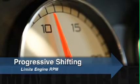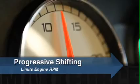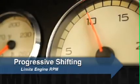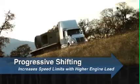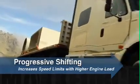Progressive shifting limits the engine RPM to require earlier shifts. When activated, it will feel like a power loss, but actually it's just the engine hitting the RPM limit. Once you shift to the next higher gear, you can accelerate again to the next shift point. It also has the ability to identify engine load and progressively increases engine speed limits with higher engine loads.